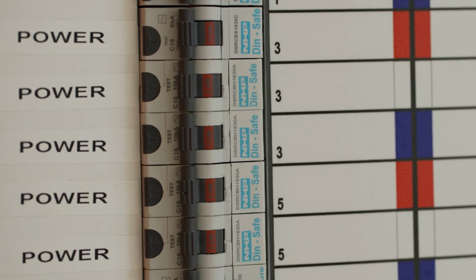Higher current levels through the protection device will ensure the fastest operation, with minimal heat energy build-up in circuit conductors. Cables and protective devices are coordinated for optimal, practical and safe operation under fault conditions. Temperature rise in cables must be limited to prevent heat-initiated fire.